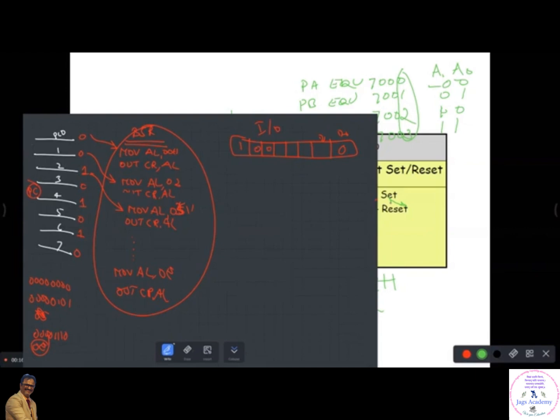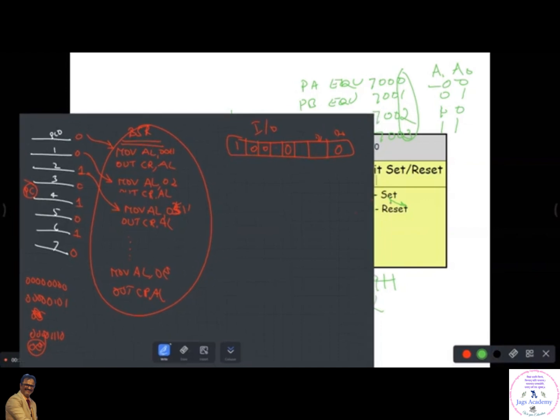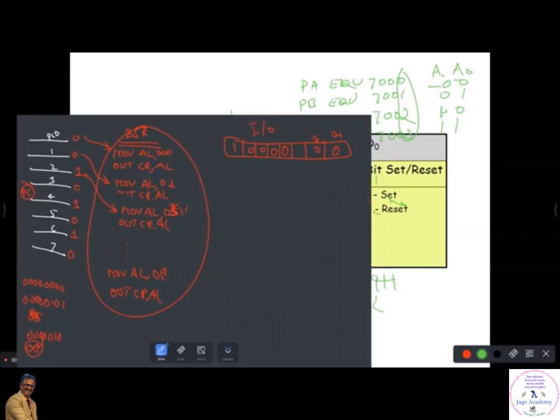Okay. What about two? Two bits are very important for you here. What is that? Port C lower, port C upper. And both port C lower and upper you are making 0, output, right? So this corresponds to port C lower. Which bit corresponds to port C upper? D3. D0, D1, D2, D3. This is also 0, right? Right. You make all of it 0. Don't worry about the ones you are not using. Can you tell me what the control word is? 80. 80 is the control word.